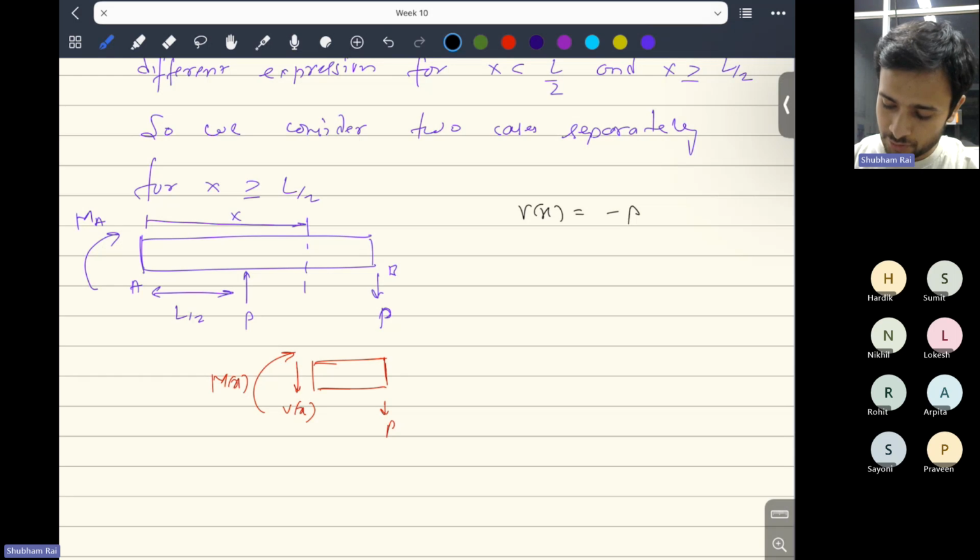And if we balance the moment about this point at the center of this element to the left hand side, so this mx is actually positive bending moment. Bending moment means, if we talk about stresses, this will contribute to the same kind of stresses that this kind of moment on this face is going to contribute, because stress is a tensor, it's going to depend on face normal as well as the direction of the traction.